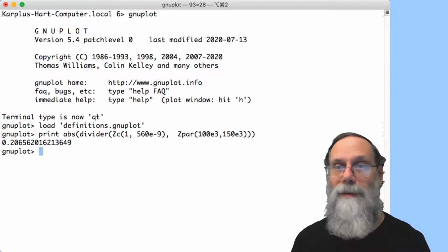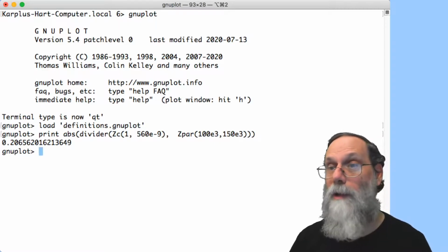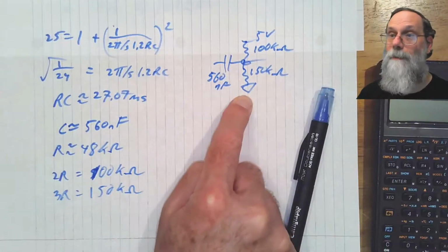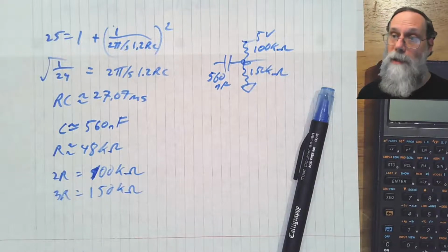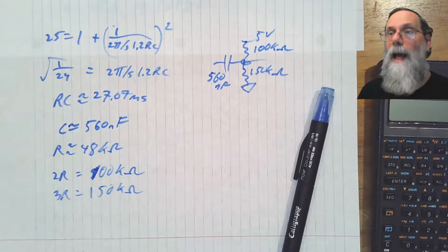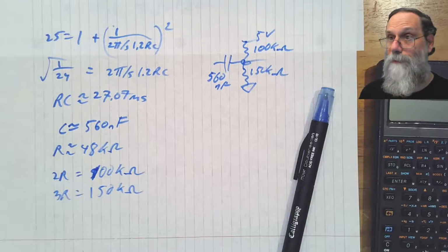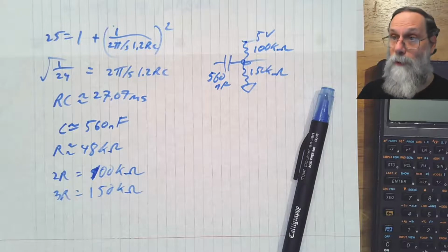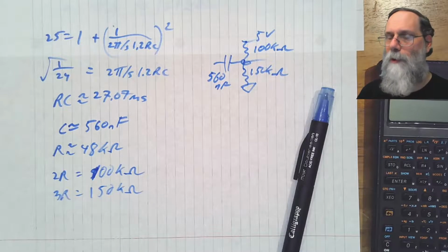And everything here, I've got the right voltage now coming out, I've got the right gain at 1 hertz, I've got my design. There it is. Now, what made this example more complicated than most of the ones that you'll be doing is that I had specified a gain at 1 hertz that was not that easy to achieve without going through some algebra. Quite often you'll have much easier specs, like somebody will give you the corner frequency, where the gain is approximately 0.7, 1 over the square root of 2.